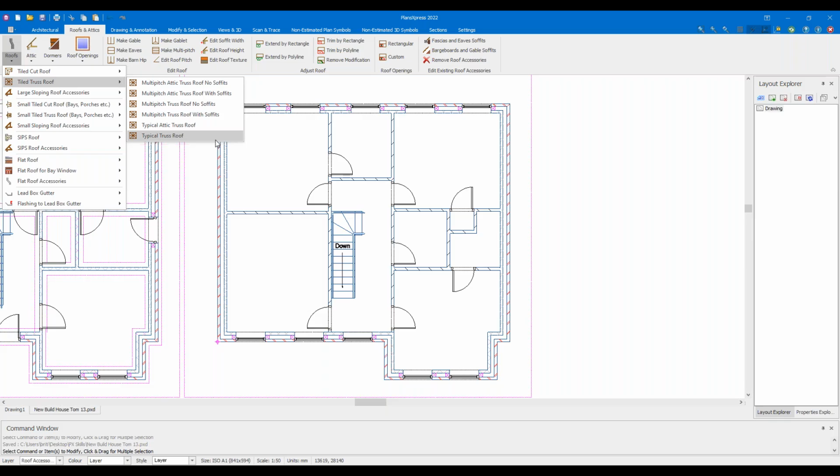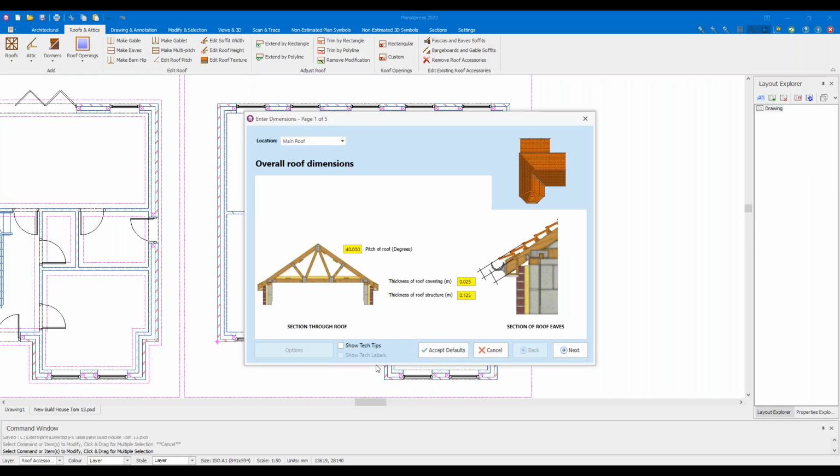A couple of other things to keep in mind with a truss roof. You can't do vaulted ceilings, unless you're using a particular type of truss. So you might be able to draw in some cut ceilings for vaulted in there, or attic ceilings on a certain level. But we can also get away with having a slightly thinner timber there as well, just because of the way trusses are manufactured. It does give us a roof pitch of 40 degrees.